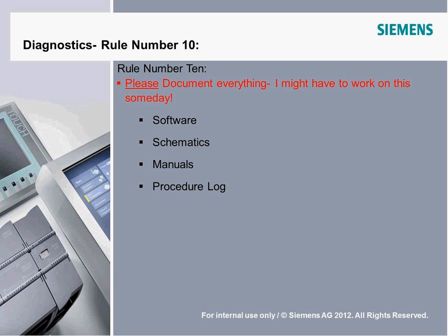And then milliamps are better in that it's in a single path loop, an output back to a return signal. You get the same current level throughout that circuit as long as there's not multiple paths in it. What that means is that we don't care so much about voltage drops and so forth. With 0 to 10 volts, you could have 9 volts coming out of the PLC and 8.5 showing up at the actuator because of the resistance of the wiring. 4 to 20 milliamp, within reason, will compensate for resistance in wiring, so that when you send out 4 milliamps at the PLC, that's 4 milliamps that shows up at the actuator.